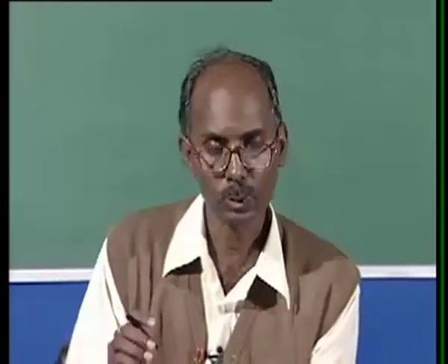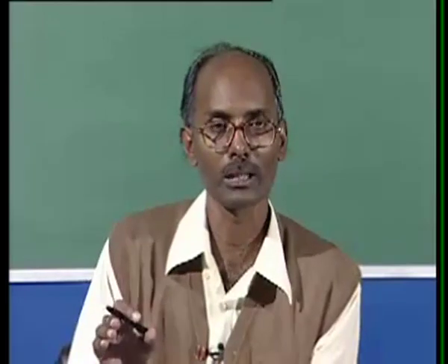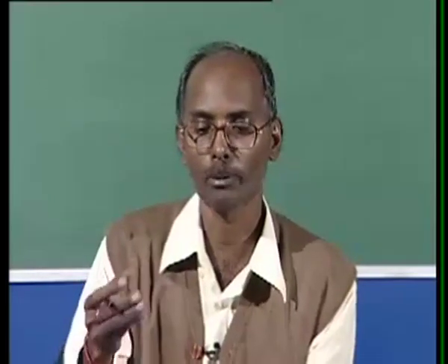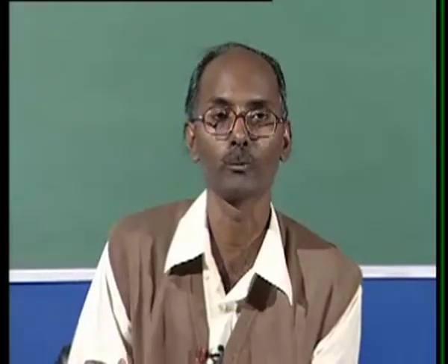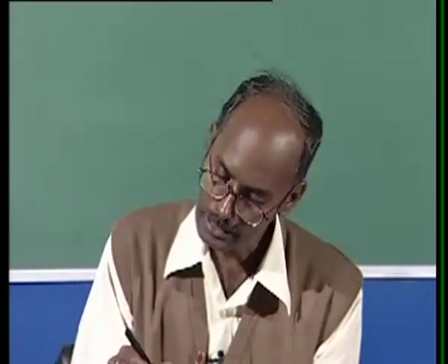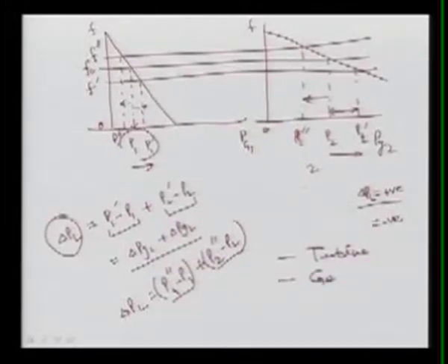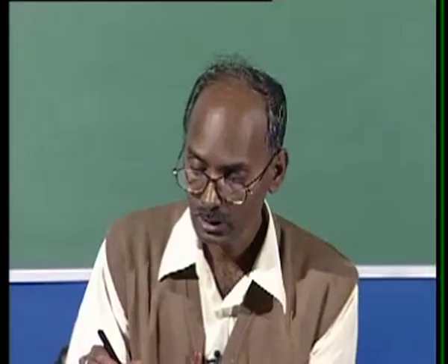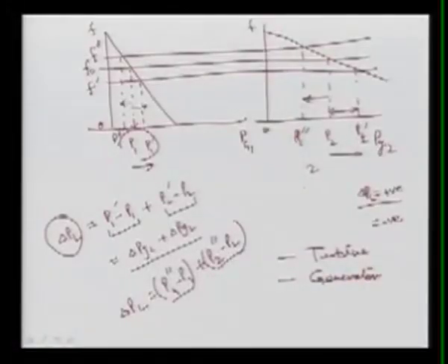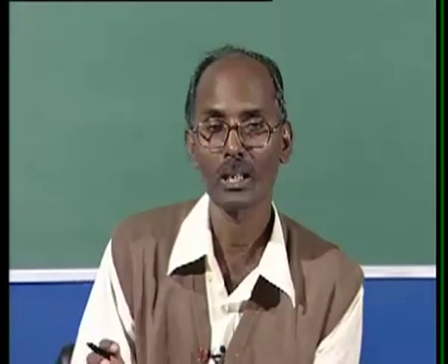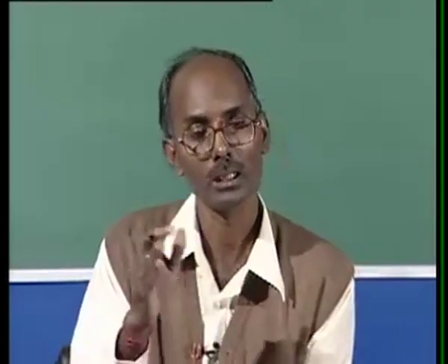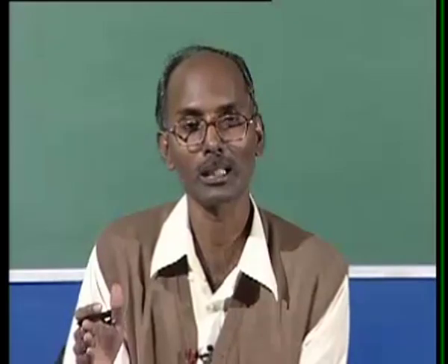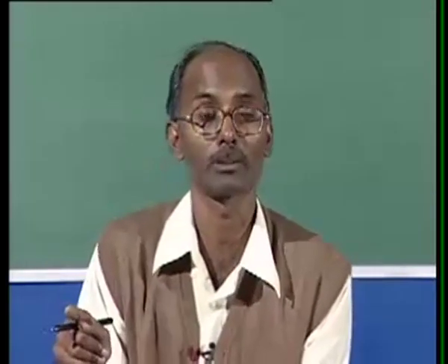Later on also I will use the turbine modeling without reheating, so that we can see the performance of the system, or the various loops, that is the load frequency control loops. I also modeled the generators along with the rotating mass of the turbine, so it is generator plus turbine rotating mass, and then we related the turbine output to the electrical output, and that electrical output is related with the frequency of the system.